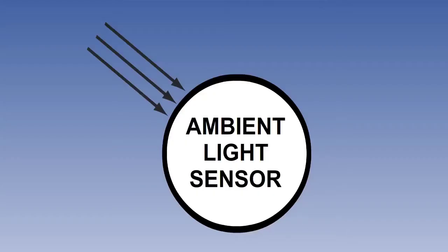There is also an ambient light sensor, similar in principle to the one employed in EFIS, to automatically control the brightness of the HUD presentation assembly. It maintains the initial brightness level selected by the pilot, and therefore adjusts for changing flight deck light conditions during the flight.